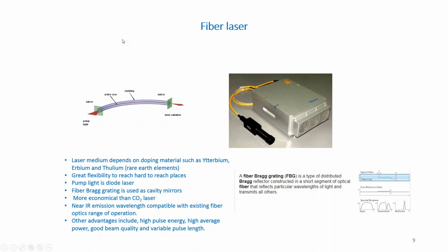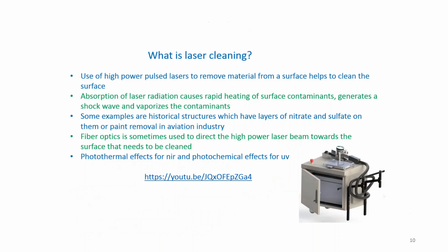You can also get femtosecond fiber lasers that can be used for removal of contamination from composite materials. You have to be careful not to damage the fibers inside the composite materials. So for this reason, you have to use either a UV laser, or if not available, you could use a femtosecond fiber laser. This way, you would only remove the contaminant layer, and you won't damage the bulk or the reinforcing fibers within the body of the material.